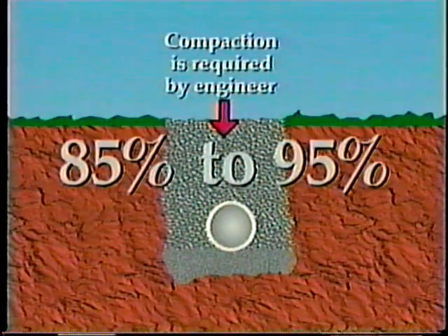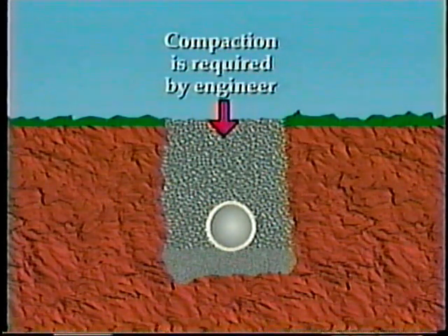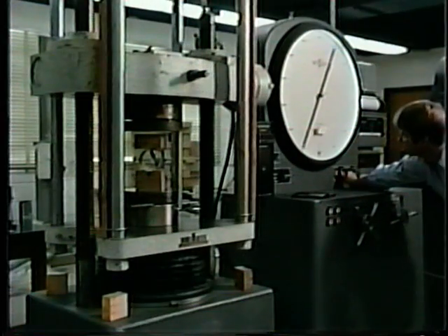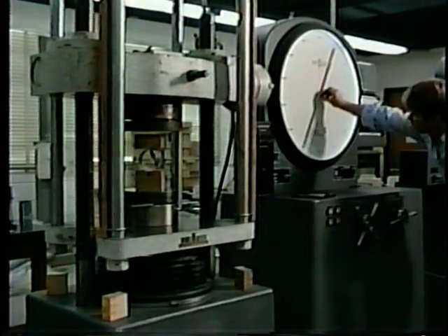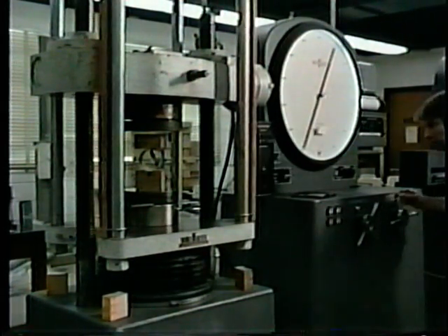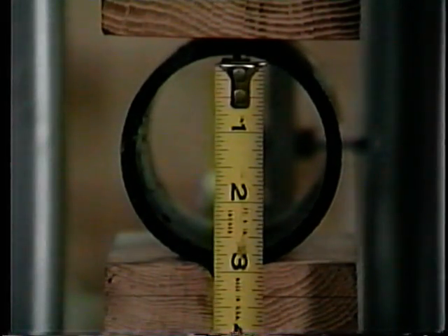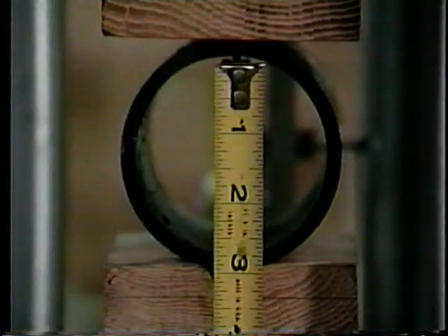If the installation does not have suitable backfill available that can be compacted, it must be brought in from another source. Measurement of this critical compaction is not easily accomplished. Deflection in all piping materials must be controlled to prevent flow obstruction and assure that joints remain secure when earth and traffic loads upon the buried pipe occur.